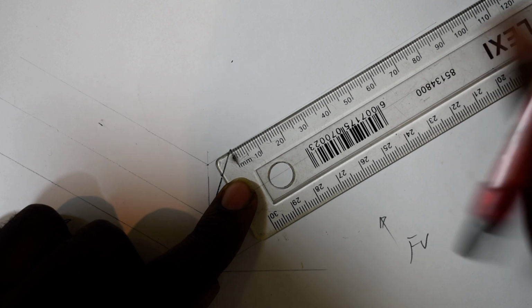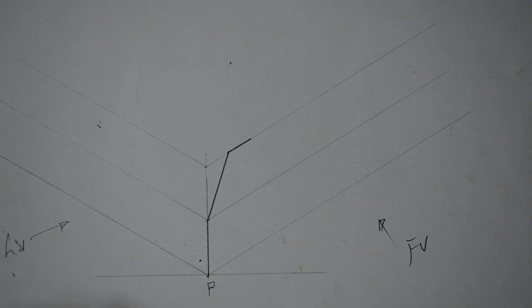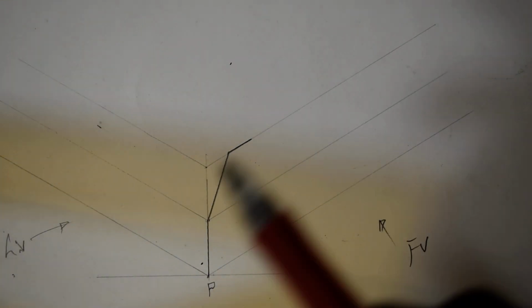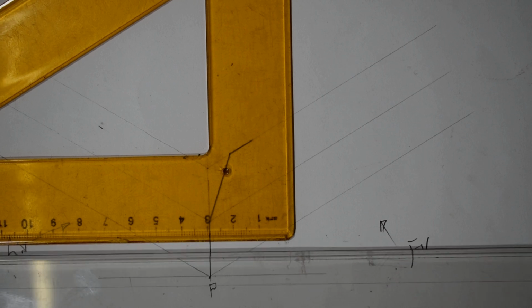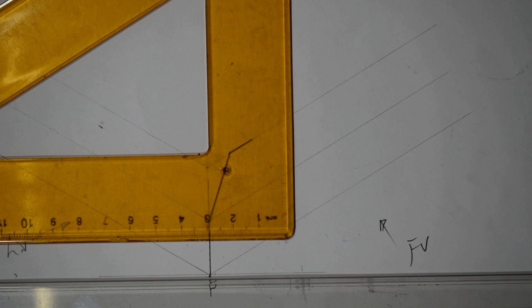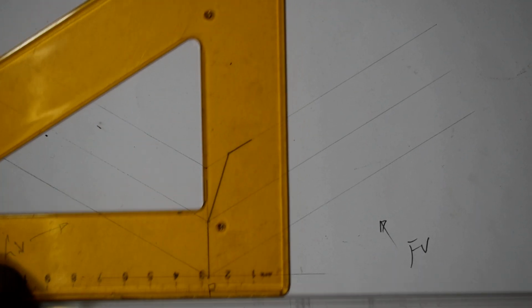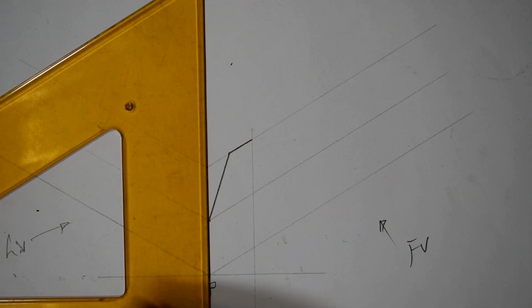and I can draw it from here till here. Right. So where your 10 ends, I see a vertical going down line of 20. You understand? Of 20. So you follow this. Remember that this T-square of yours must always be attached to the head of your drawing table or your drawing board, and your set square must always flush along. You understand? So now I can construct it down. Finish. You get it?